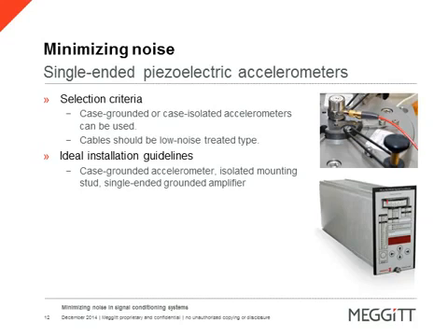An ideal installation includes the choices of one, a grounded accelerometer, two, an isolated accelerometer, three, the use of an isolated mounting stud, and sometimes more importantly, you could have an amplifier such as the 2775B to the right, which has a switchable isolation for the front-end signal conditioner for the different sensor types. And this concludes my portion of this presentation. So Jim, please take it from here.